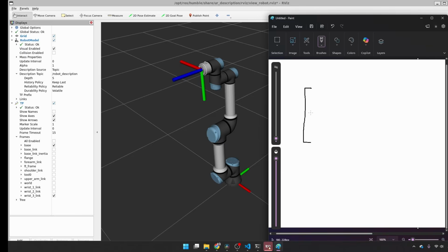So if we want to see the direction of the x-axis of the tool with respect to the base frame, what we see here is that this x-axis, which is in green, is pointing in the opposite direction of the base. So I could say this should be -1, and then the other components should be 0, 0. Okay, so that should be the x-axis.